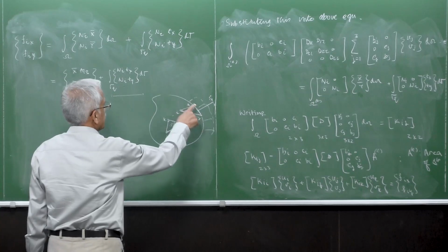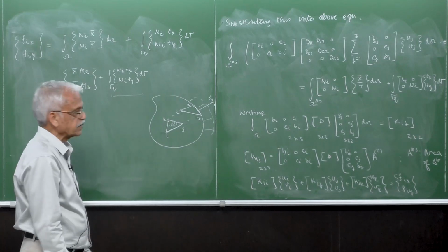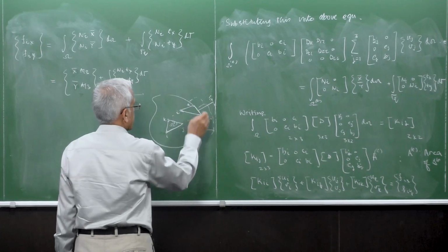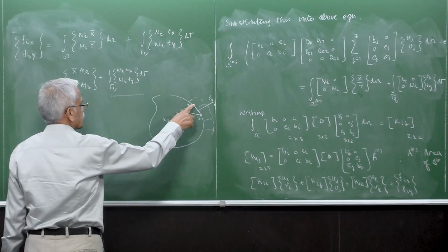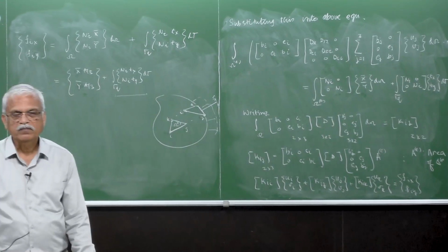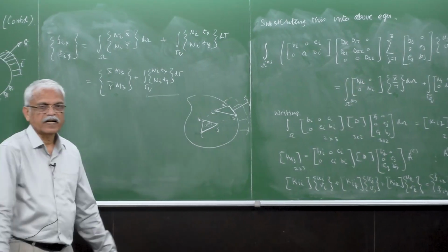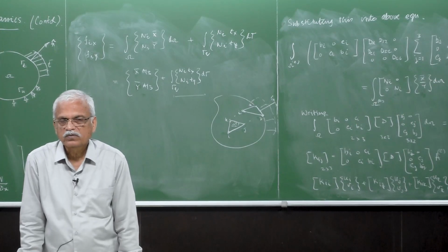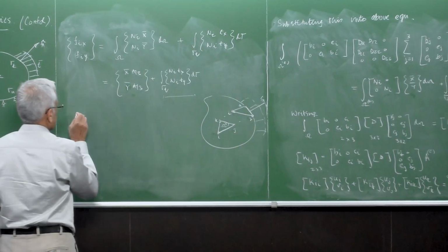If the element edge Jk falls on this traction boundary condition, so we know that the Nj here is having a value of 1 here and goes to 0 linearly to k. So its integral along this side will be simply sjk by 2. So sjk is the side length, and if you integrate it, varying linearly to 0, it becomes half. So similarly for this one. So the contribution